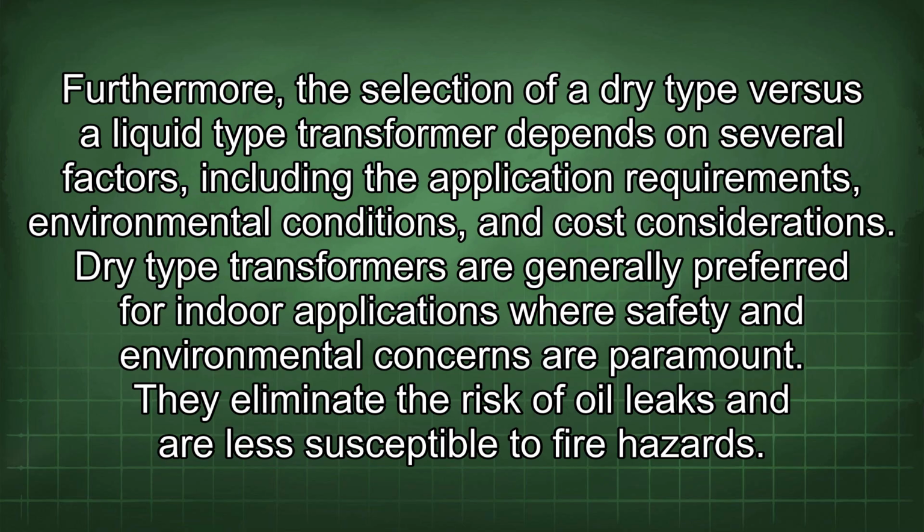Furthermore, the selection of a dry-type versus a liquid-type transformer depends on several factors, including the application requirements, environmental conditions, and cost considerations. Dry-type transformers are generally preferred for indoor applications where safety and environmental concerns are paramount.